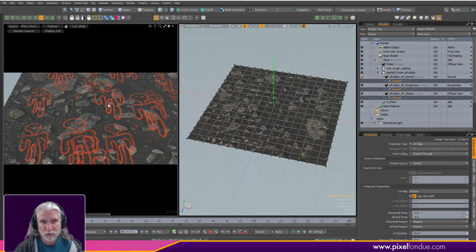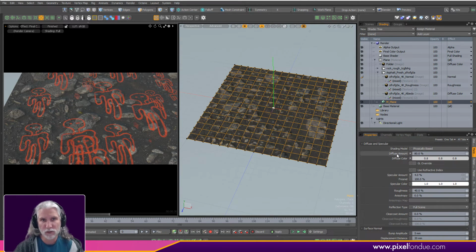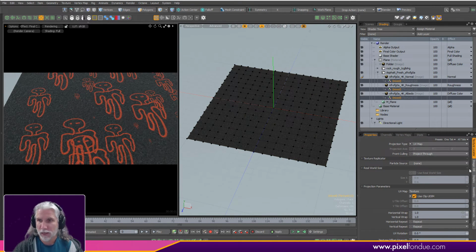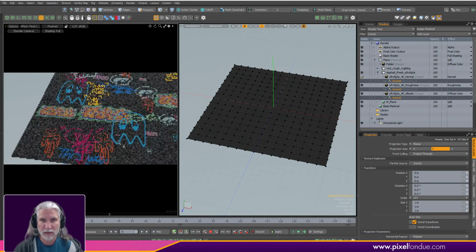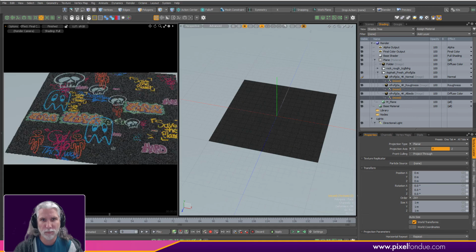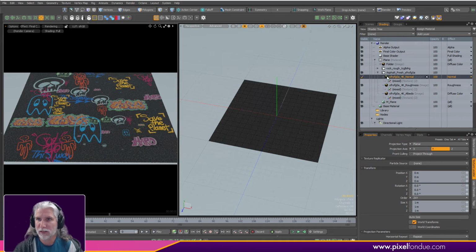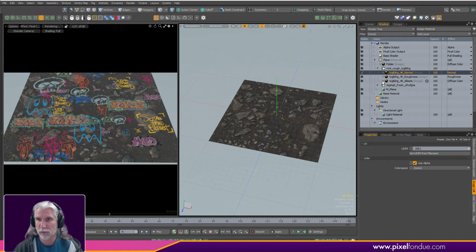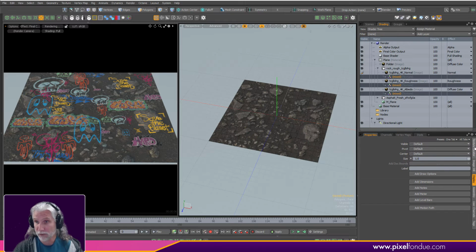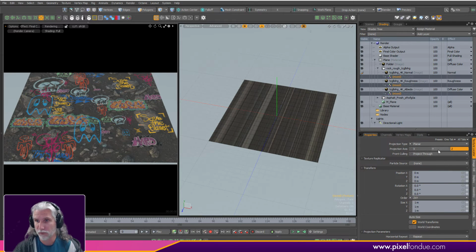So they're set to UV, and we lose all our texture variation. It's just grabbing one image. But if I grab these texture locators for this asphalt and set them to planar, we get all our different images back. So that's that weird bug I was talking about. If it's mixed in with UV projected textures, for whatever reason, we lose our planarness. So if we're going to do different textures here, just make sure they're projected. So not UV, solid, planar, whatever.